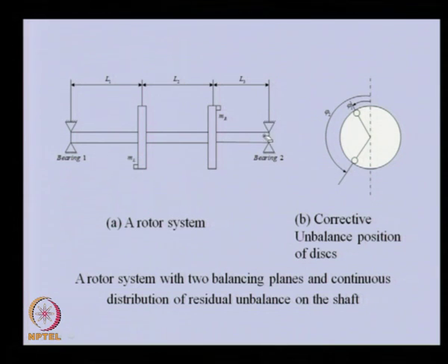With that, we will try to illustrate the method, and as I mentioned, we will model this rotor using the finite element method, and all the responses we require will also be generated with the numerical simulation. And because we need some residual unbalance, some assumed residual unbalance will be kept in this disk, and through the response we will try to estimate it.